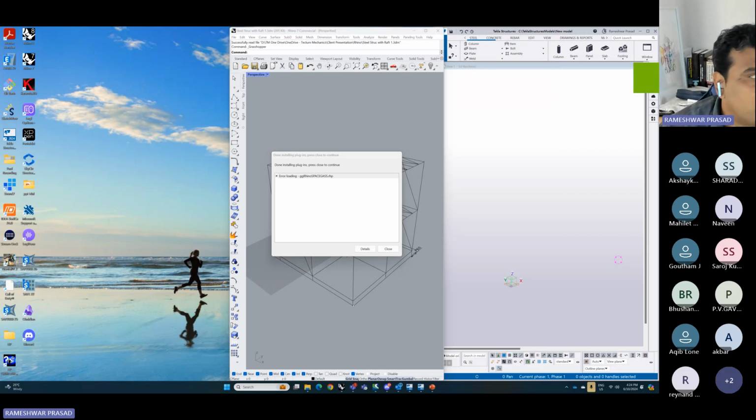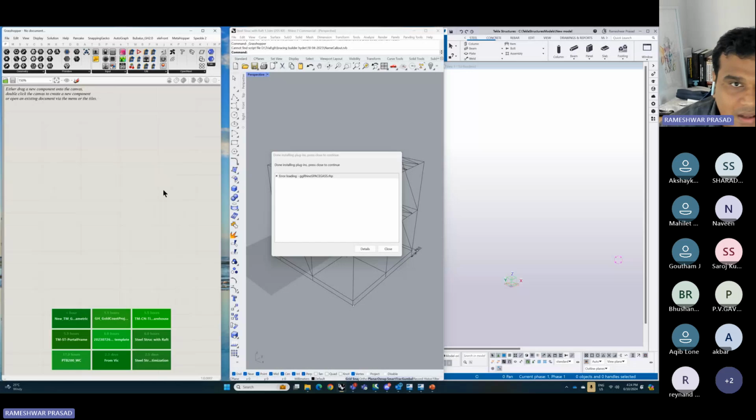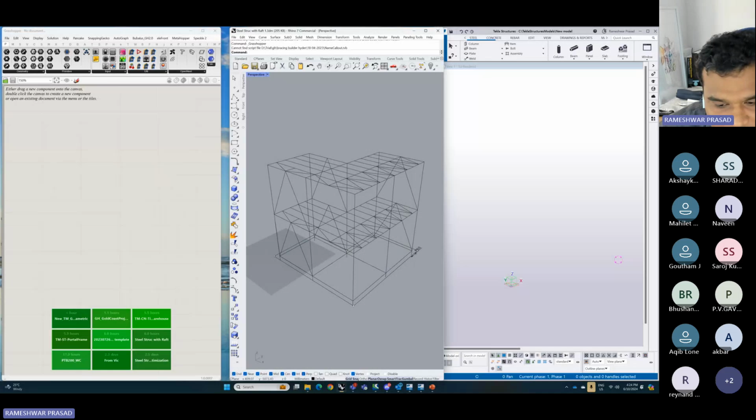If it is not responding for a brief amount of minutes, then do it. Because there will be a risk that you might be corrupting the script. And once the script is lost, then there's nothing much you can do. There are some expert programmers who go into the backend and try to derive it using XML or something. But if you are not well versed in programming, then I would strongly suggest to be patient with scripts. Especially once you start incorporating Tekla scripts, then it really does get slow.